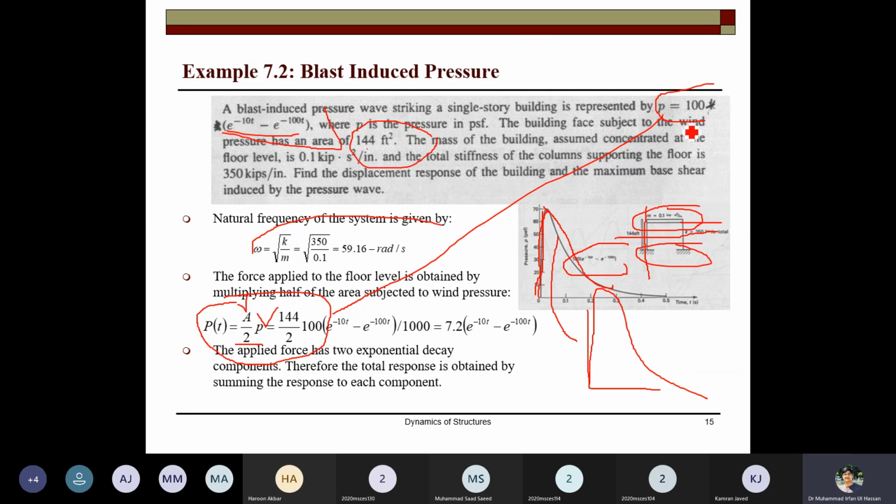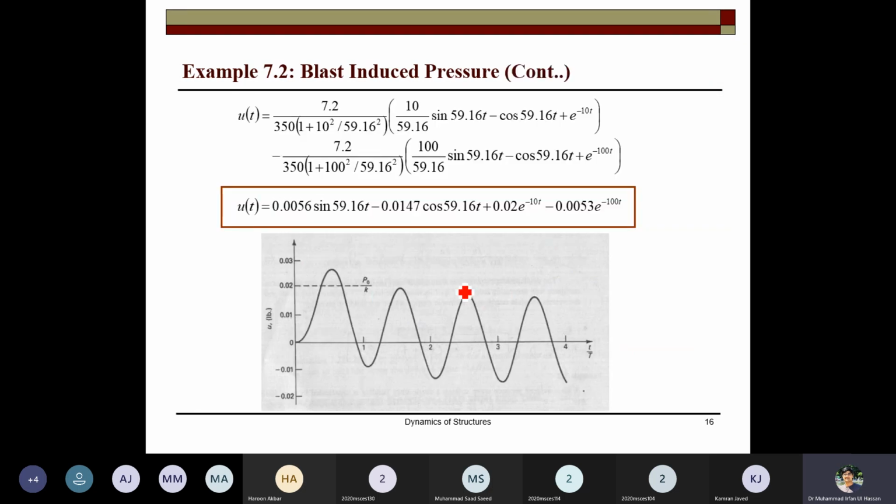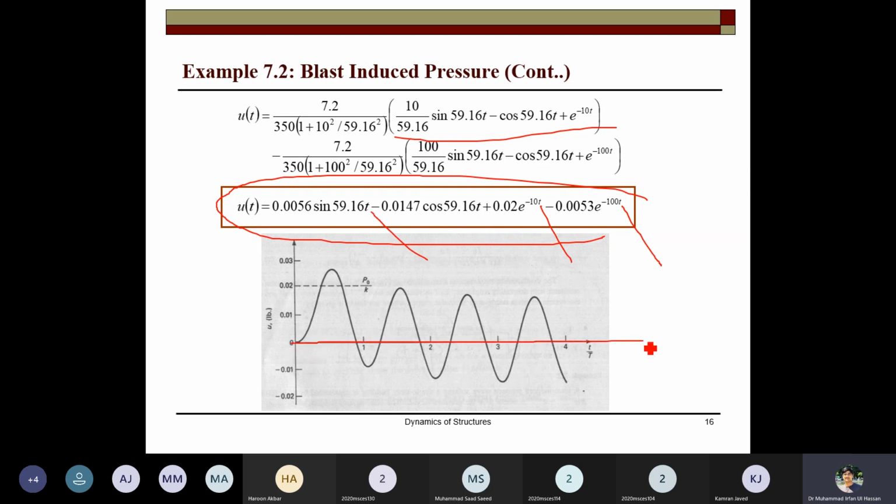Now this is the force. Now you apply in the Duhamel integral the force multiplied by dt, the time increment, and this is the force function, and then you can solve the response. Just t remains the variable. Now you take the MATLAB file and take the variable t, any range, 0 to 10 seconds, and take u on the other side. This value equation is there and you can plot it. This is the response of the system against the blast loading.